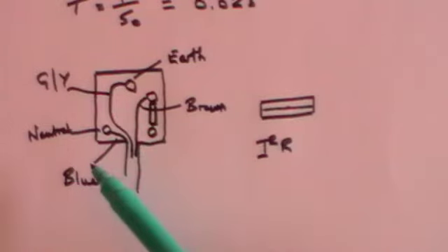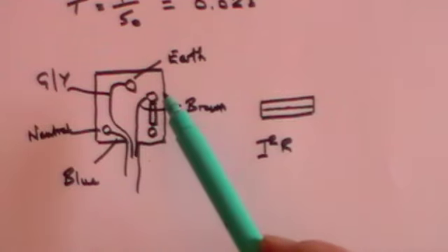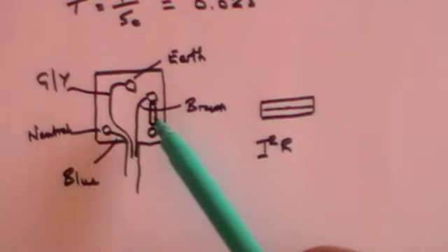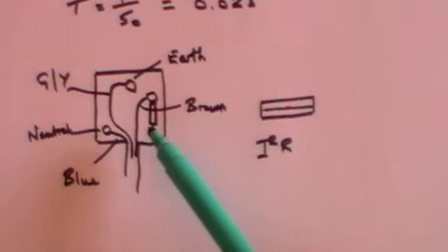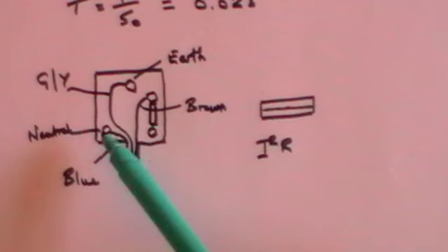But remember this, it's an alternating current. So in other words, the current is at some point going through the brown cable and sometimes going through the blue cable. So even if the fuse burns out, there's still a possibility for what we call the neutral cable to give you an electric shock. So don't think that the neutral cable is entirely safe if the brown cable is disconnected. There can still be danger in the blue cable. The general rule is, when the plug is in the socket in the wall, do not interfere with any of the cables.